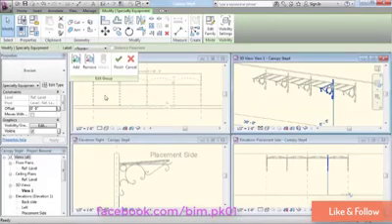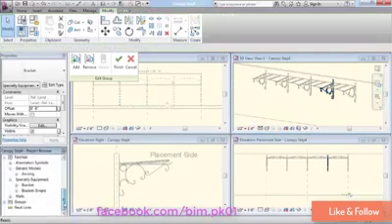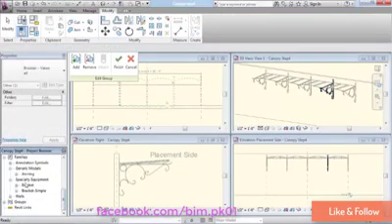So rather than just change it outright, I'm going to make it a parameter so that we can swap it in and out on the fly. Now you may recall at the start of this tutorial that we loaded in 2 versions of the bracket. We had bracket and bracket simple as families in this file.